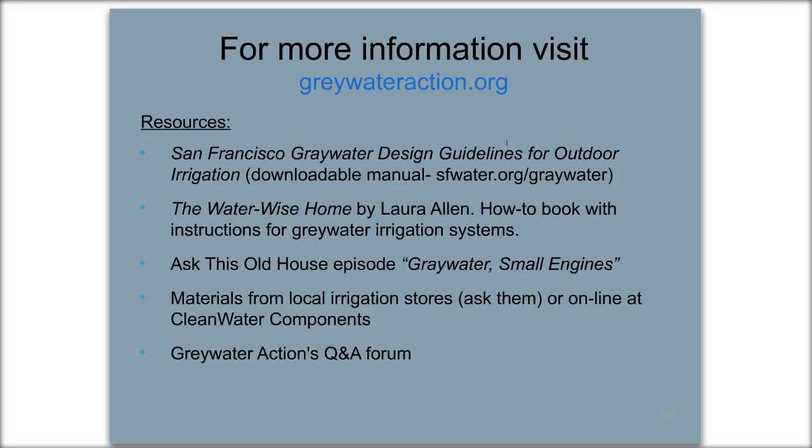Is any old free tree mulch I get from tree trimming services sufficient? And how far does water soak through a mulch basin? And how far apart should outlets be? Yeah, pretty much any old mulch is going to work just fine. How far the water soaks through the basin does depend on your soil type, and you can observe how it soaks in. When you dig the basin, don't fill it in with wood chips. Just leave it open and then run the flow, or just use a hose to put water in and see how far it spreads out. In general, if you have any type of clay soil, the water will travel all around the basin, so you usually only need one outlet per tree and the water will spread throughout the basin. If you have sandy soils, water goes down much quicker and it doesn't spread out as much, so you would want to be closer to the tree and potentially have more outlets to put more water around the plant.